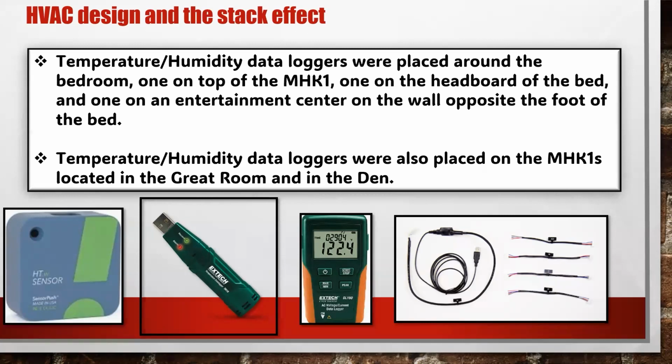The ceiling is about a quarter inch out of level on the short side, not the long way. On the back side, it's hanging down about a quarter inch and then flush to the ceiling. We're going to put some tapered trim in there, but you can't hang the unit not level. Oh, right, you nailed it. Trim kit.